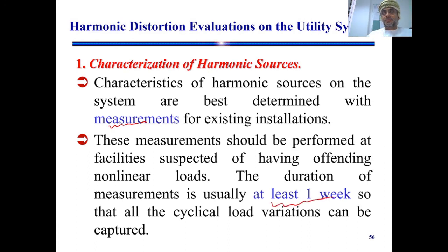So we need to bring our power quality device and connect it at the point of common coupling, let us say, or at the user in which we suspect that there is a source of harmonics coming from this user. Keep it for 1 week so that all cyclic load variations can be captured by those devices.